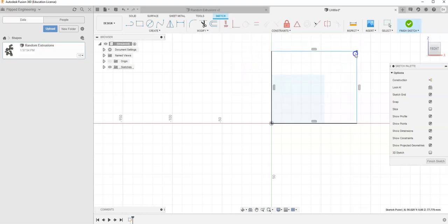And I can start playing with my rectangle tool again. Now, you'll notice 2 of the lines have turned black and 2 have stayed blue. There's a very good reason for that. I've constrained these 2 lines to be stuck to this point, but I've put no such constraints on these 2 lines. I can change where this point goes. I can change where these lines are. I can change the sizes of these lines. And so blue lines represent not constrained, and black lines represent constrained.